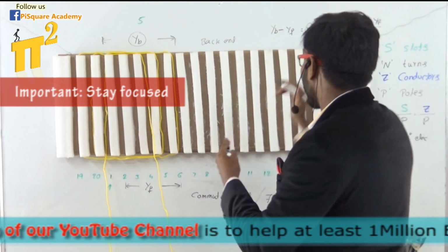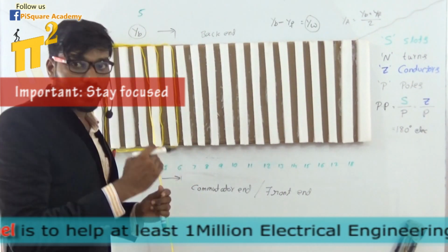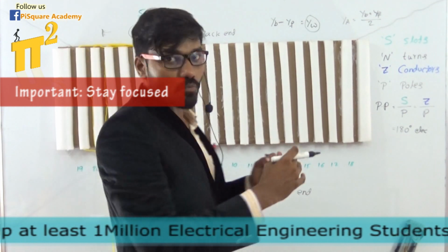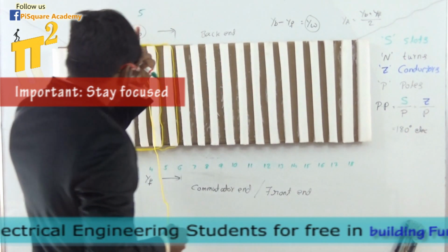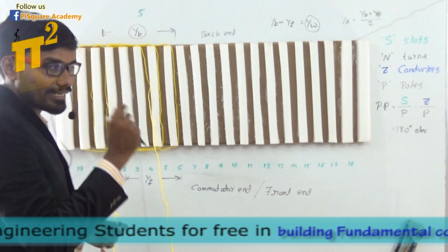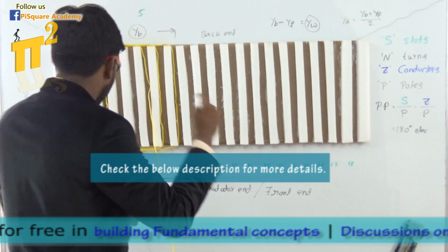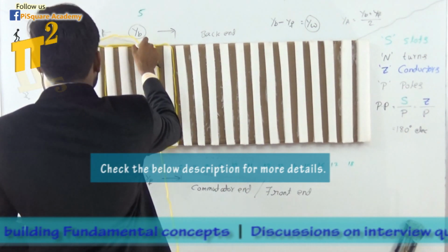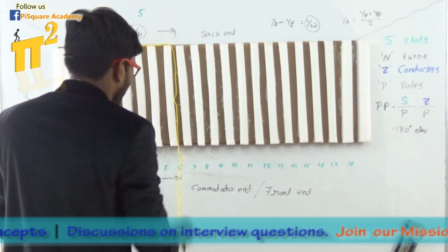If the winding pitch is less than the pole pitch, then it is a lap winding. If the winding pitch is more than the pole pitch, then it is wave winding. So the winding pitch indicates the type of winding, hence it is called so. There is another pitch called commutator pitch. We'll discuss that later. I hope progressive and retrogressive are clear now.